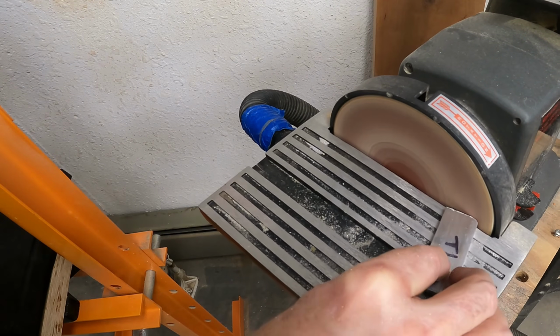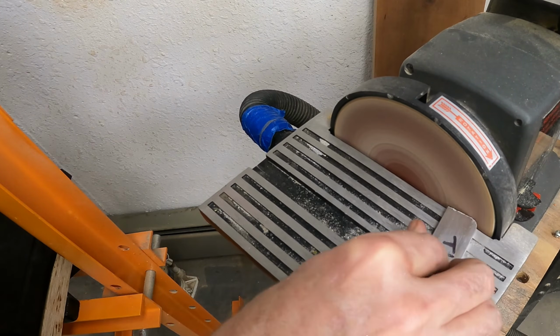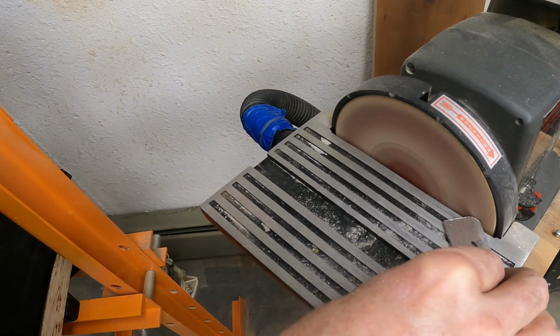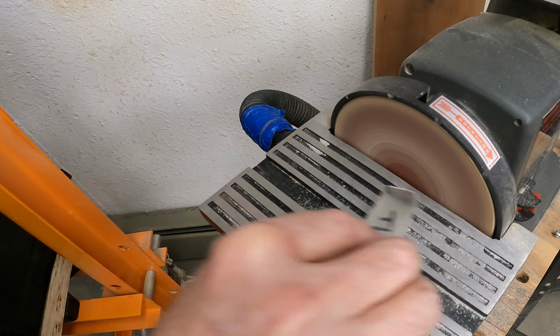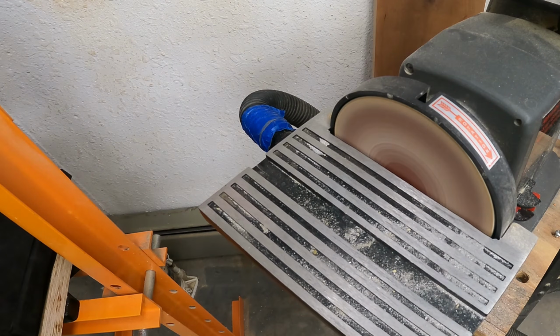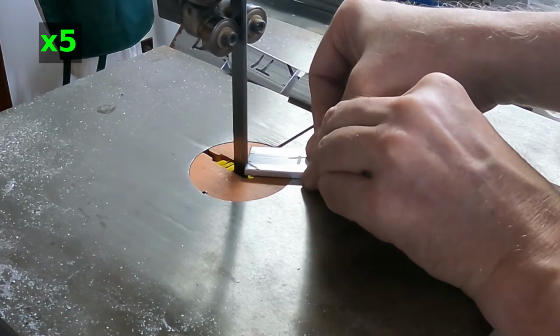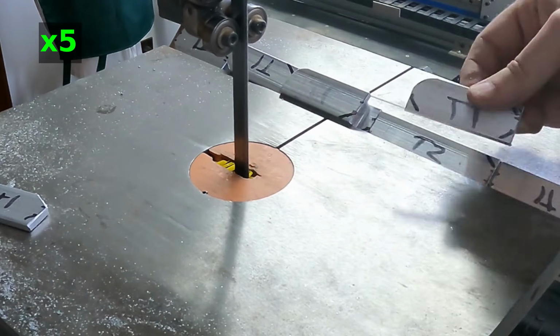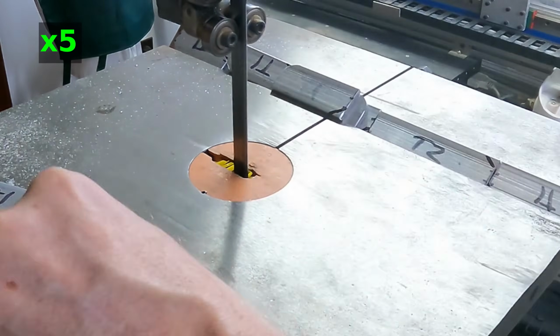Now for these load ties, the pieces of metal that connect the various stringer levels together, my initial thought was to use this sander again to round off these corners, but I was going to go up to a 1/2 inch radius instead of 1/4 inch. Well, with the bigger radius and the thicker material, this is 125 thousandths, they were getting really hot fast, and it was taking a long time. So I finally gave up on that, went over to the bandsaw and cut the corners off.